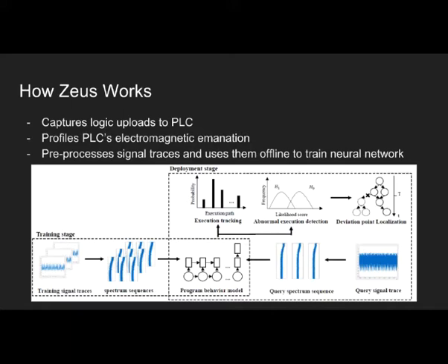I wonder whether the newer PLCs are beginning to adopt code signing and these kinds of things to address such issues. Our smartphones do it. There's no reason that PLCs can't. Technologically, it's not that we don't know how to protect software. It's cost and all. PLCs sell for around $100, $150. When you saw it, it's a Cortex M3 or something. These are pretty low-end embedded devices, so it's the cost and all.